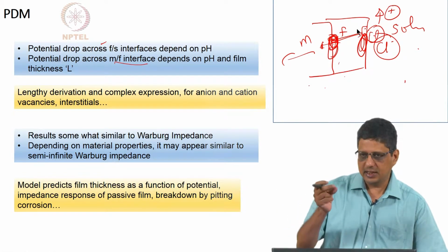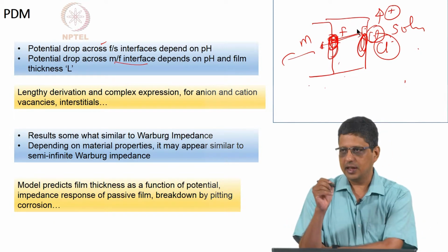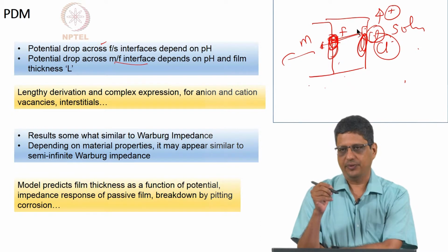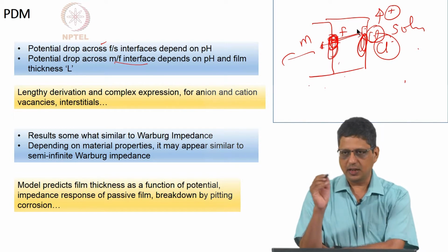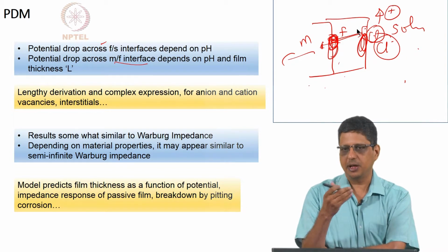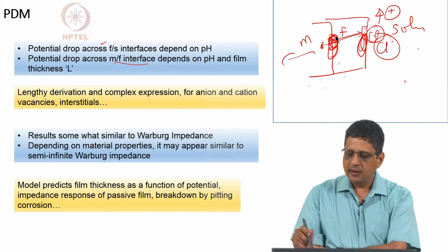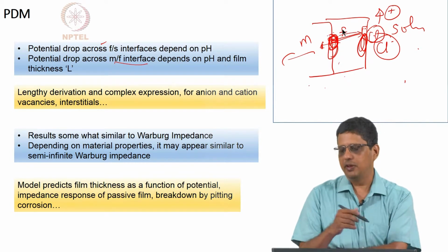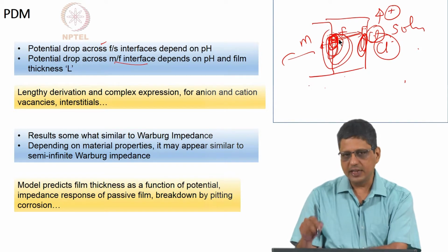It may accelerate in some specific locations where the grain boundaries meet, or certain cases where it is easier for it to accelerate. In other places, it may accelerate to some level, but not to a large level, only in certain locations because of some weakness there, meaning it may be a grain boundary, or it may have some other defect already present. It accelerates and cation vacancies which are formed here will move by diffusion and create a void at the metal film interface, and then the void grows. So, the void actually grows from inside the film.